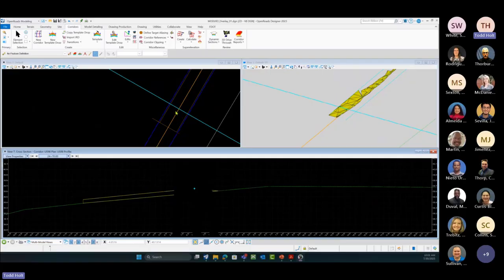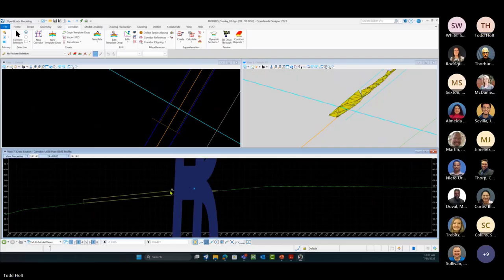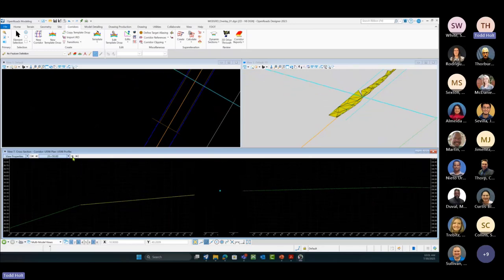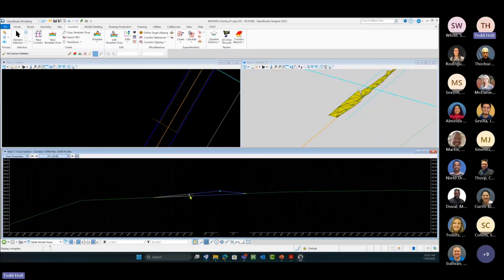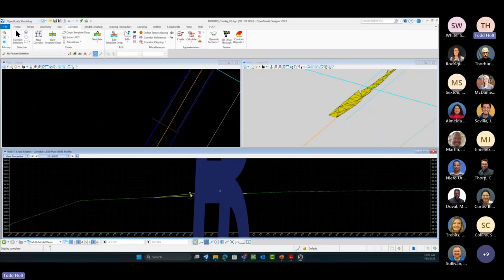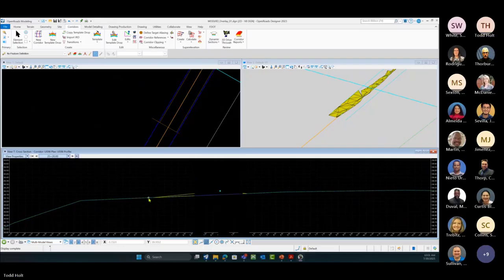Right, so in this example of where we are, to get to our new pavement design from our existing ground, this overlay is building up to the bottom of that. So if we're trying to match this slope, we'd have this much overlay that we would have to build into that in this particular design. And if we kind of walk our way through that, we can look at the different areas that would build in there. So we're holding the 2% slope off of that.